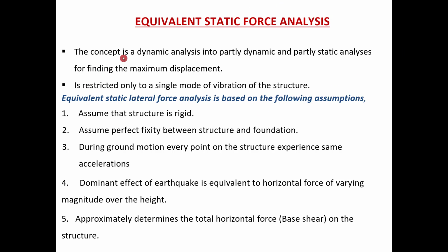So, the concept of dynamic analysis into partly dynamic and partly static analysis for finding the maximum displacement. We already mentioned that there are two methods for finding the earthquake forces. One is a dynamic analysis, which is the accurate one, but time taking and difficult process to perform the analysis. The equivalent static method is basically converting the dynamic forces to very equivalent static forces. And the limitation of this is it is restricted only to single mode of vibration.